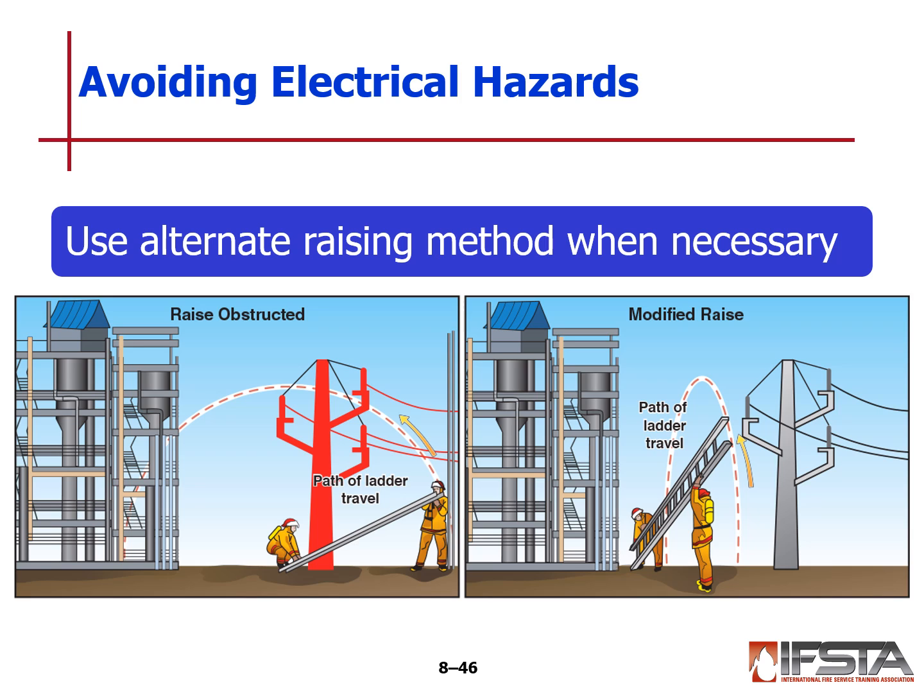You may need to use an alternate raising method in an area where we might choose to do a traditional raise. We may end up using a beam raise, and that's one of the reasons why we train you to do a beam raise, is in confined quarters in spaces such as alleys, and the other is for the modified raise is to keep you out of service drops and power lines and energized equipment.